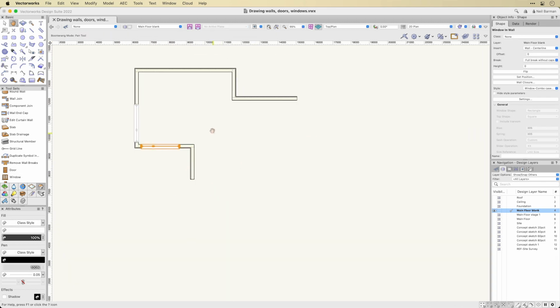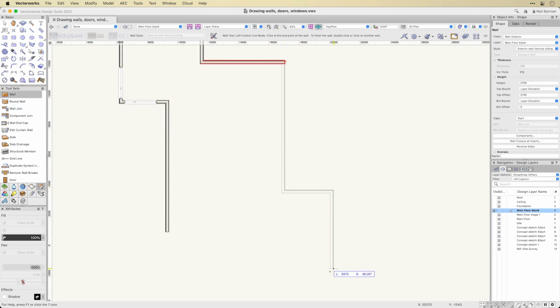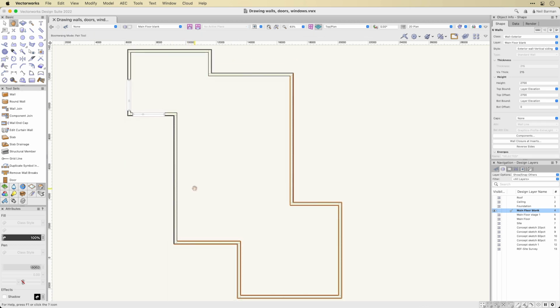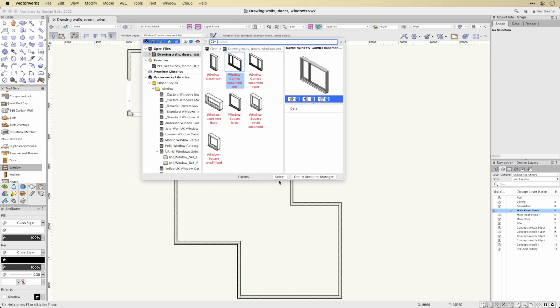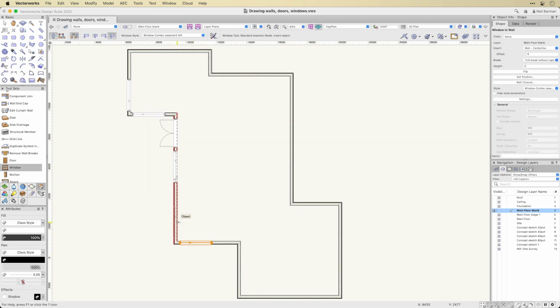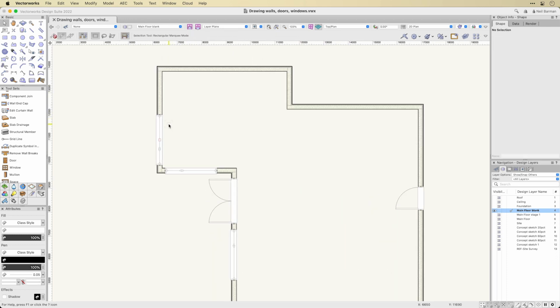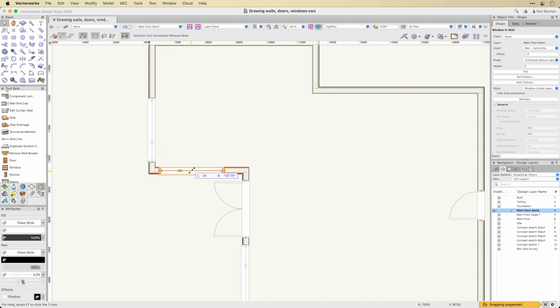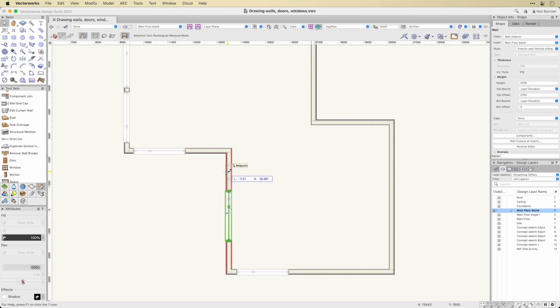You don't need to draw individual lines and shapes to fill the space between them with a color. In addition to the wall tool, the door and window tools work in the same way. You can place them while in 2D plan view, and they will insert into walls with all the lines and fills that are set for each type of object. They are also aware that they can be inserted into walls, so they automatically create openings in walls where they need to. As part of this relationship, walls will automatically heal when you delete or resize a window or door. At the same time you are doing this, those walls, windows, and doors have heights and other 3D aspects built right into them as well.